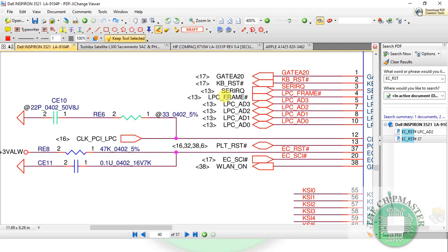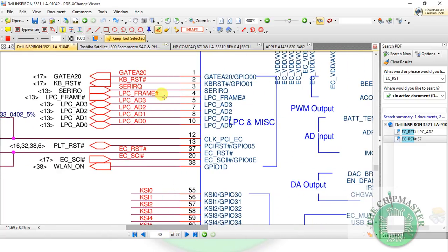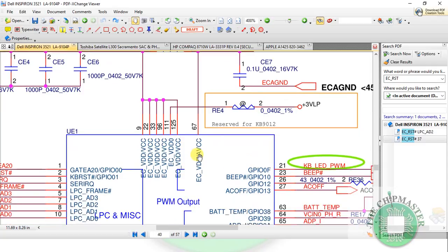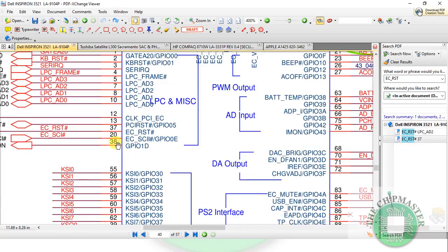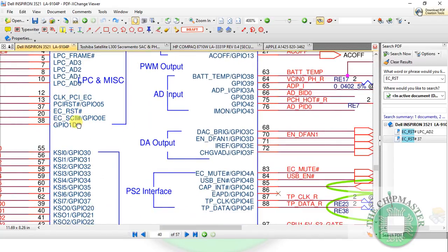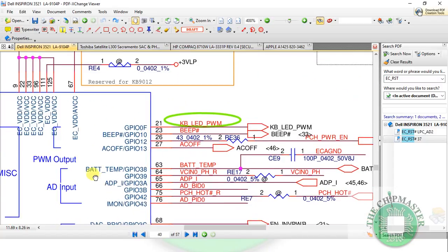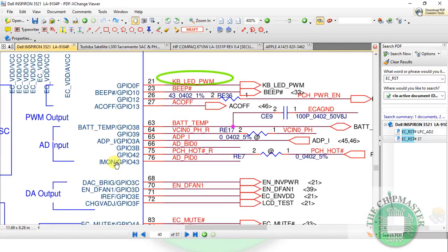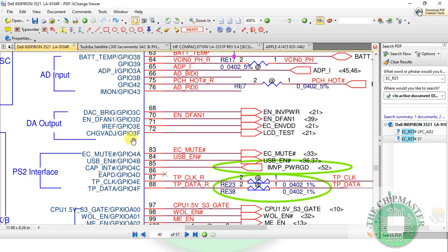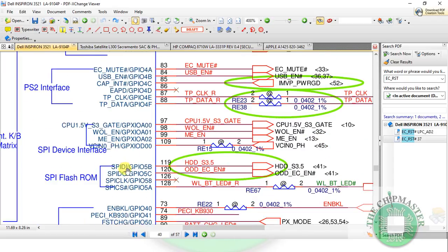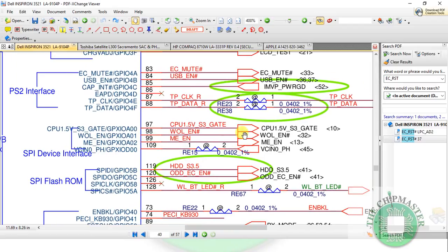So if the program is abnormal or corrupted, then they cannot turn on the machine. But for pins like AVCC, the EC reset pin, supply, reset, and integrated clock, if you notice, there are no GPIO pins beside them. If you look at these other pins, you see GPIO 3, GPIO 4, GPIO A, B, C, D. All these signals are defined by the program. It has an input, it's an output. We have incoming signals, we have outgoing signals.